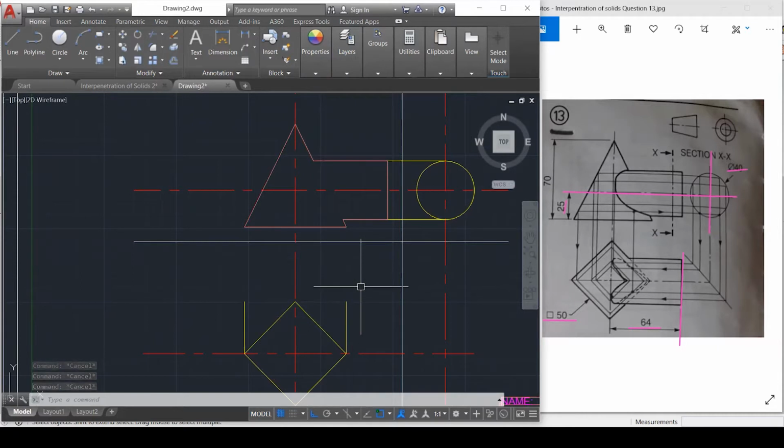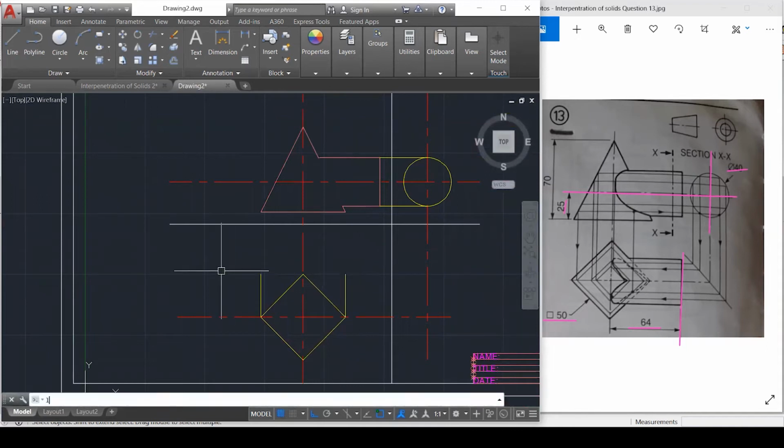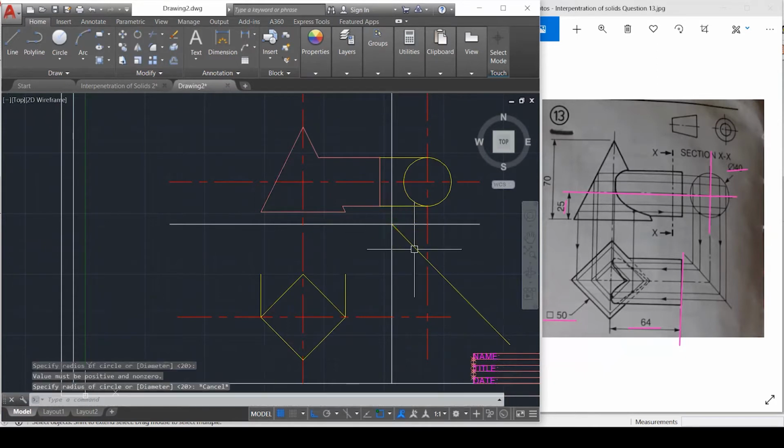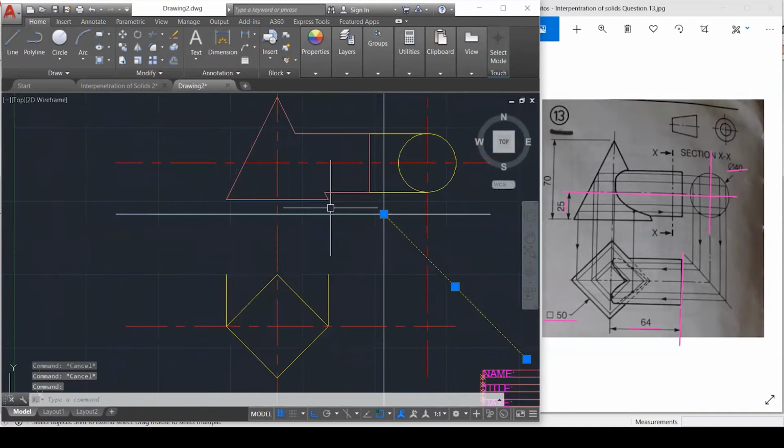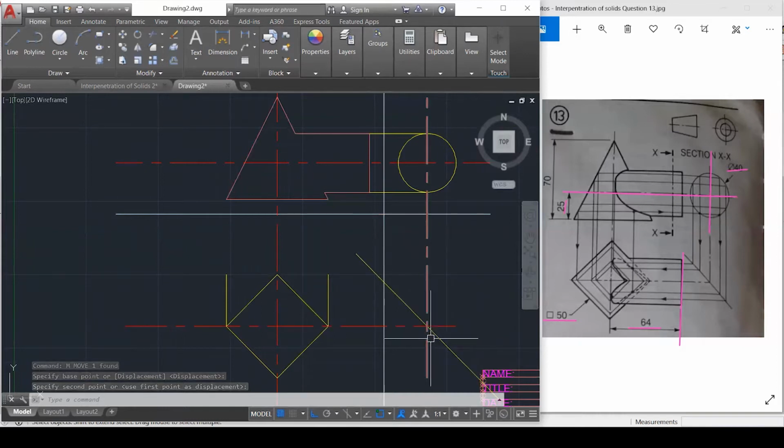So that's very important. So I've gotten that in as a shape. What I'm going to do now, I need to put in my information line here, which is going to be at 315 degrees. That's the same thing as a 45-degree line, but it's mirrored in a below region. All right, so I'm just going to let people know what that is. This is a 45-degree. Actually, no, my 45-degree line isn't going to go right there. I need to move that. Why do I need to move it? I need to move it and coincide it right here, because that is where things go perpendicular at this point here. So you gotta remember that.